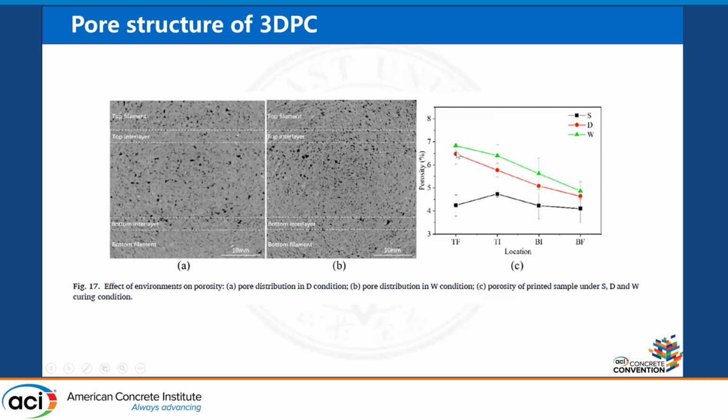We can see that on the top of the specimen, we've got much higher porosity than the bottom, and for the interlayer, the porosity lies between the top surface and the bottom.